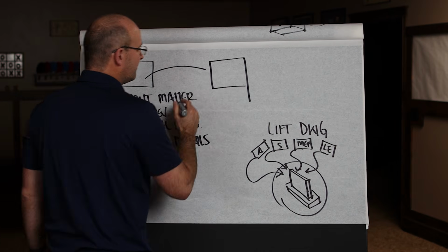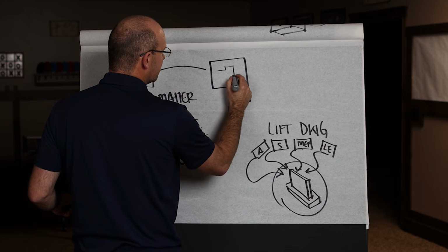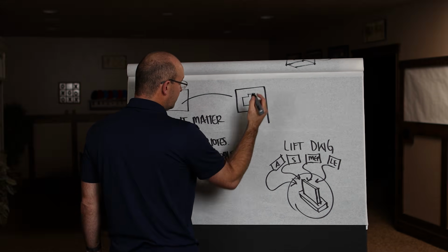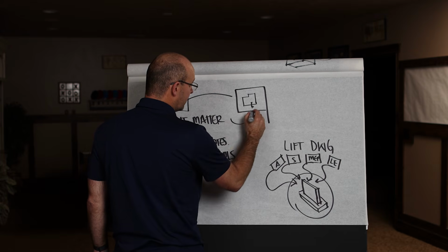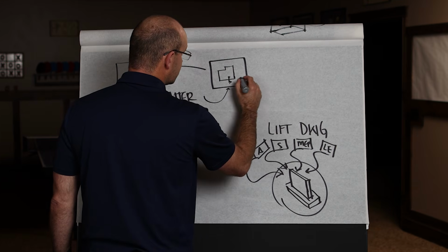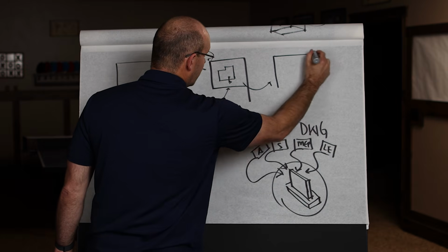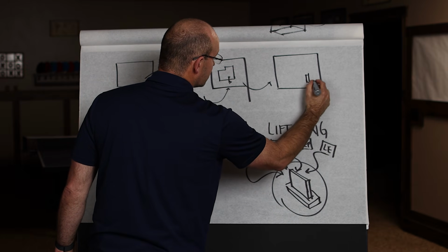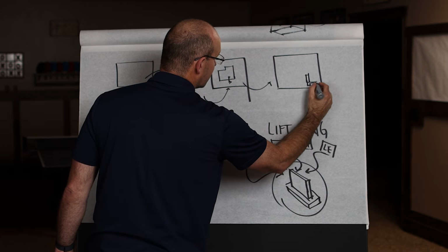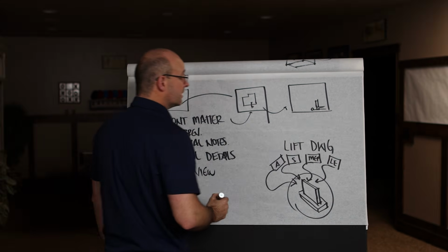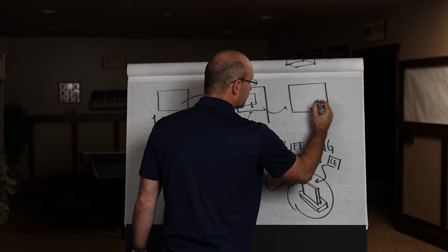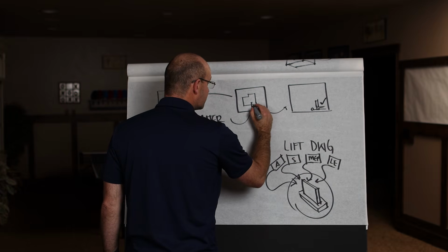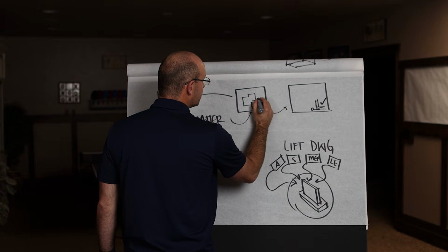But if you have a plan view, and let's say this is the outline of your slab on grade or something, and you see a detail in here, I would say go to that detail, okay? And go look at the associated page where that detail points to. Like let's maybe say this is a wall section and here's the slab on grade or something like that, and then here's the actual cut section. Go ahead and research all this, and then you can highlight it or put a check mark, and then move to your next detail.